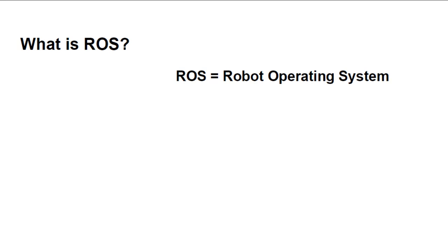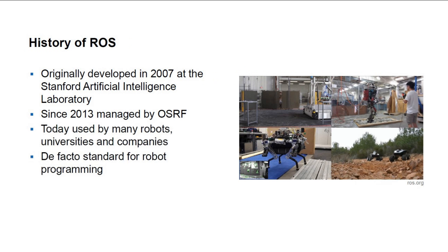Okay, the key feature of the Robot Operating System is the way the software is run and the way it communicates, allowing you to design complex software without knowing how certain hardware works. ROS provides a way to connect a network of processes, meaning nodes, with a central hub. Nodes can be run on multiple devices and they connect to that hub in various ways.